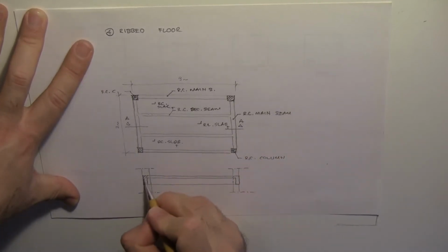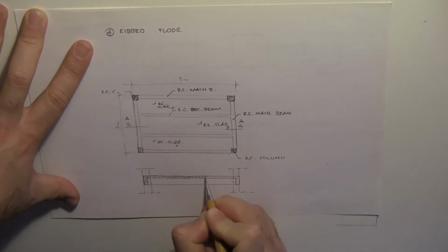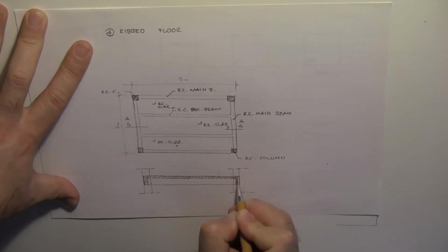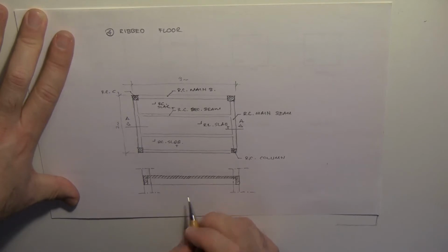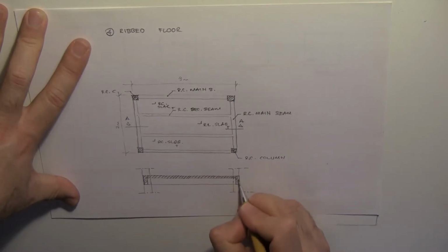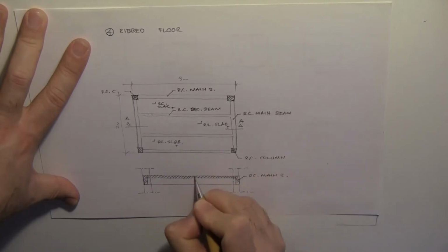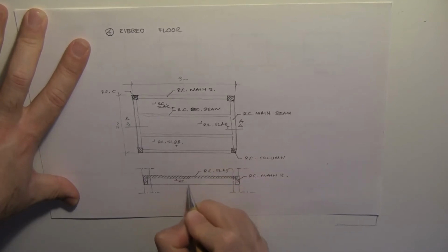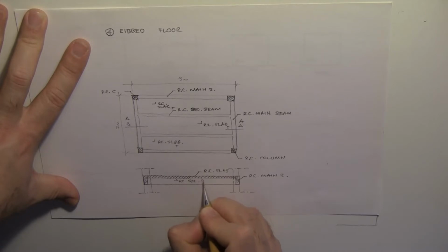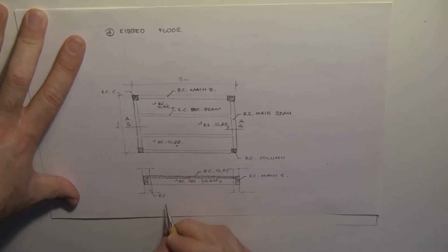So what do I have now? I have got my reinforced concrete slab here, which is 15 centimeters minimum, and it is being supported by my secondary beam made of reinforced concrete. Let's write the names. This is reinforced concrete main beam, that's reinforced concrete slab, and this thing that we have here is reinforced concrete secondary beam. And of course it will be good if we write column. It's maybe the most important component when we think about structural safety.